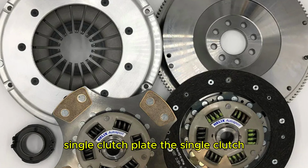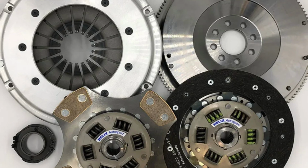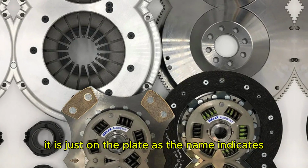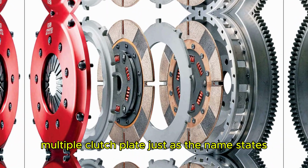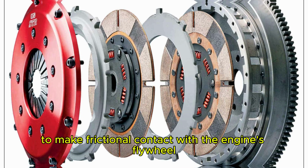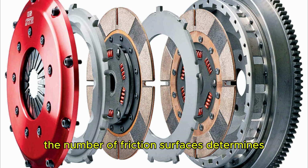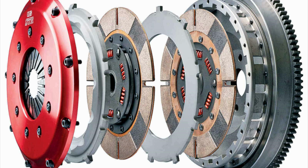Single clutch plate. The single clutch is the most common clutch found on modern light vehicles. It helps transmit torque and power from the engine to the transmission input shaft. It is just one plate, as the name indicates. Multiple clutch plate. Just as the name states, a multiple clutch plate uses multiple clutches to make frictional contact with the engine's flywheel. This transmits power between the engine shaft and the transmission shaft of the vehicle. The number of friction surfaces determines the capacity of the clutch to transmit torque.